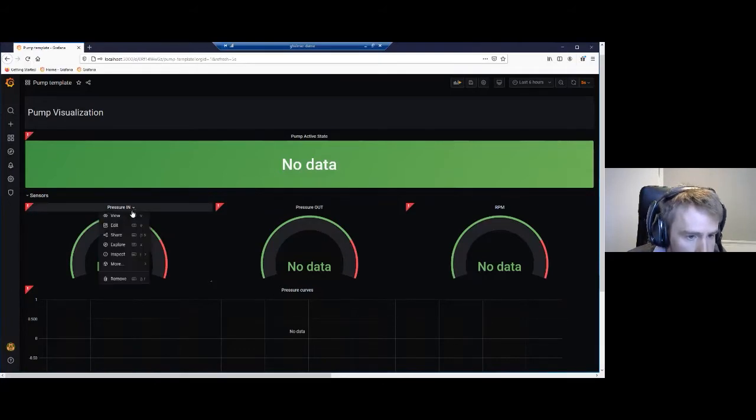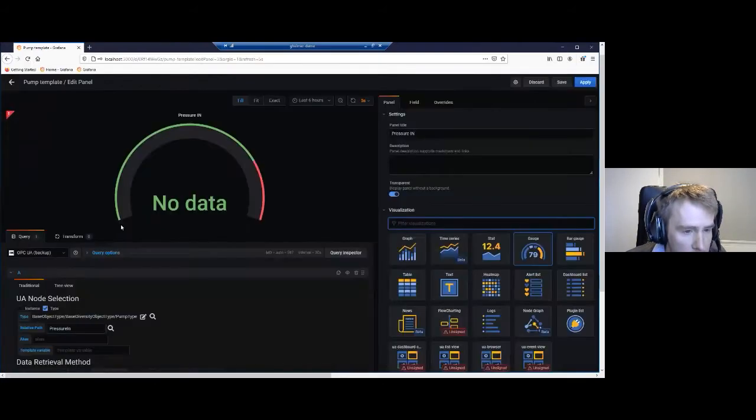And if we go here, we can look at how data should be wired to this template. We see here that we've selected the type, and we've selected that we'd like to connect this to a signal relative to the pump type. So in OPC UA, you declare what's called an instance declaration, which is saying what do pumps look like.